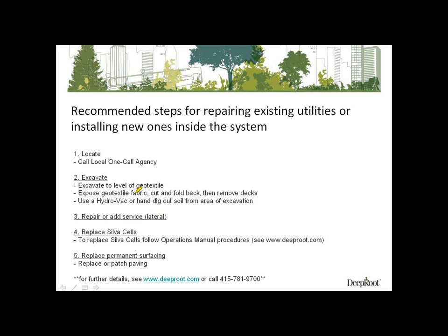Backing up to the excavation process, I talked about when it's a shallow excavation, you just take the decks off. If it's deeper, you have your choice. You can either dig out the soil or hydrovac out the soil and remove the frames and salvage them, or you can also just take out the frames, either excavate them out or just break them out as you go through, and then replace them. So it kind of depends on, one, how much time you have, two, how deep you're going or how many frames are involved, and three, the restoration effort.